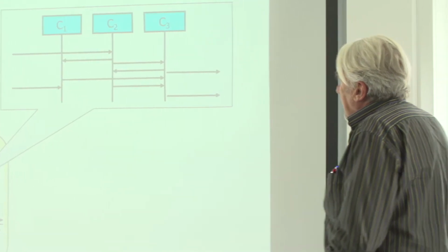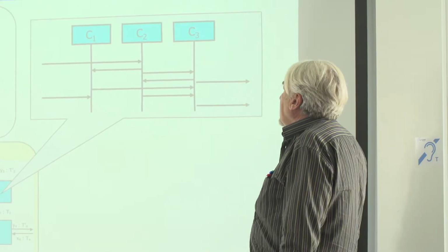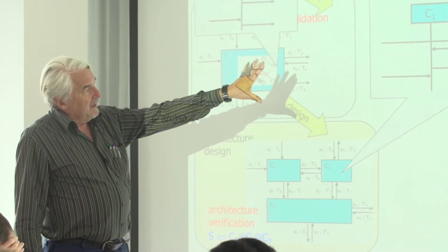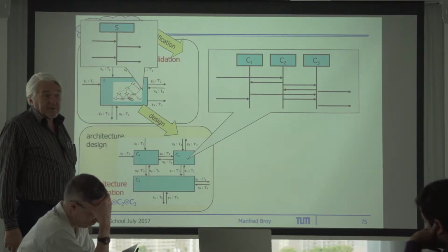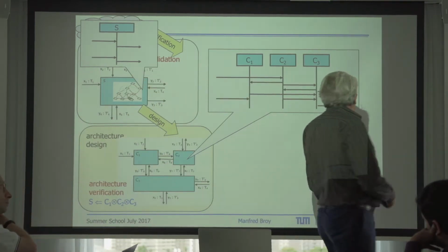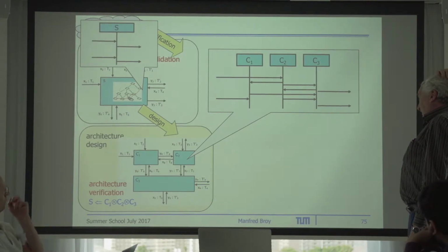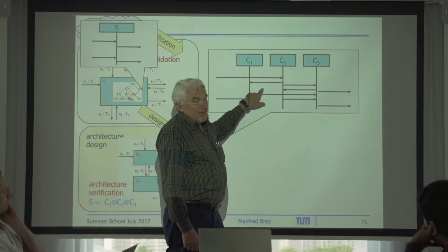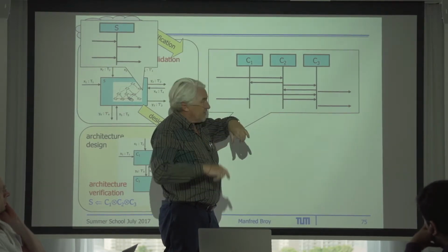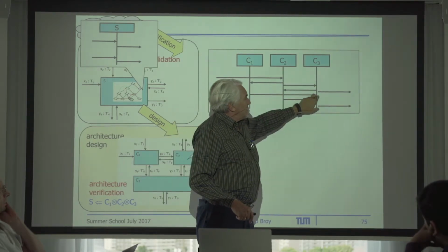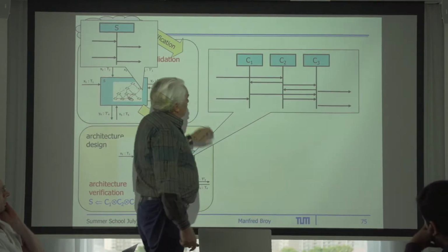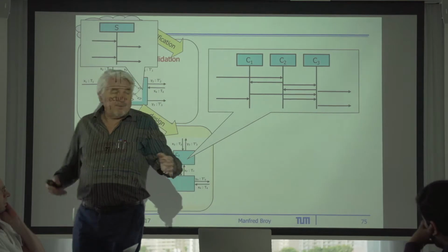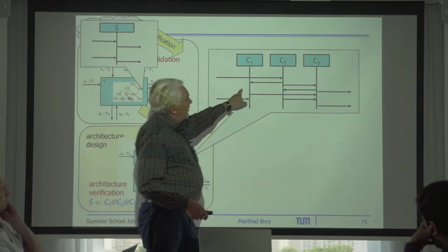OK, now we have done the architecture. By the way, here I like to work with interaction diagrams, because this describes, as a use case in a scenario, the interaction between the different components. And this is typical for a car today. If for instance, let's assume this is a crash system, then we get the crash signal. And when we get the crash signal inside the car, a lot of interaction goes on, because a lot of the CPUs start and the functions on the CPU start to talk to each other. And finally, maybe this one says, activate airbags. And perhaps there's another signal that is needed. And finally, this says, make sure that the airbags come out.